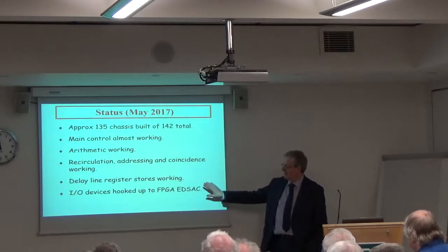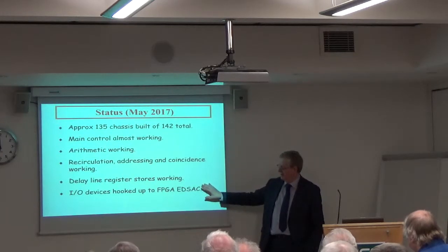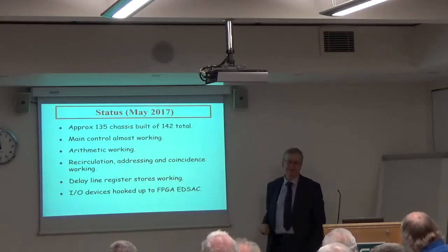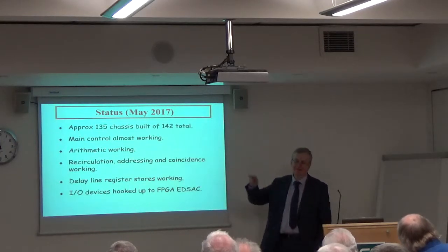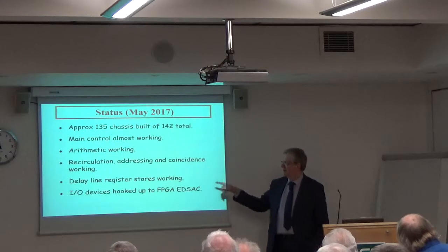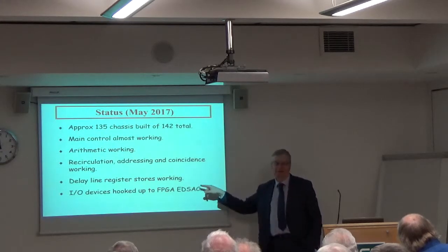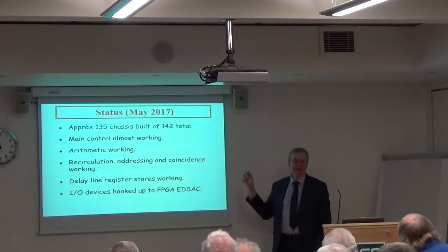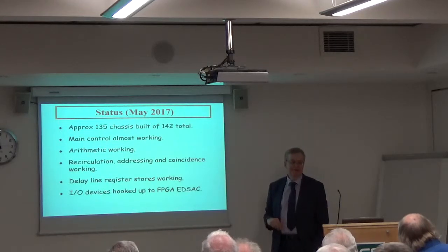And hiding behind this, the final part of the story, is the penny has dropped that there are sufficiently few control signals, and given most of the data is travelling serially, we could put a fast machine, and this FPGA might well be the right thing to build, hidden inside the machine that's monitoring all the signals. That would help us with diagnosis if it goes wrong, and potentially you could switch out the bits that have gone wrong and just simulate them.